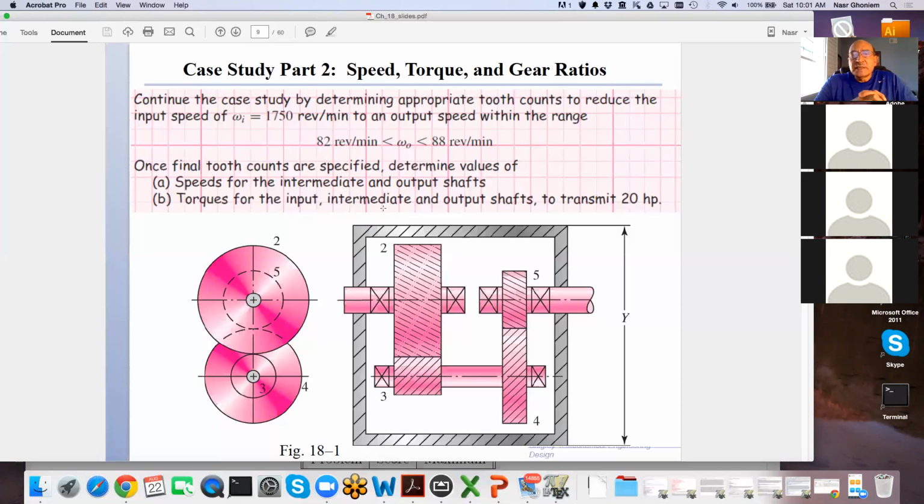It's just sizing. I'll show you the sizing first. And once we did the sizing, we say, gear 2 is going to have so many teeth, and it will have a pitch of so much, and it will have a diameter of so much. So we selected basically the gear. We can go ahead and order it online.